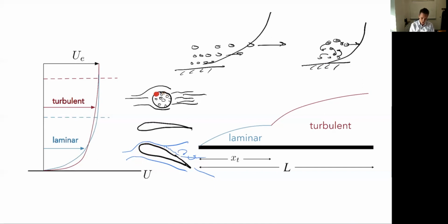So same idea here with the cylinder, right? Remember, we went from high pressure to low and then back to high. So on this backside, as I go from low to high, I'm doing work. I'm moving against this pressure. We call it an adverse pressure gradient. So I need that momentum.